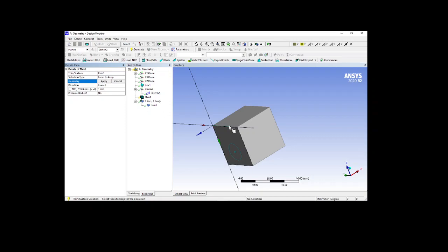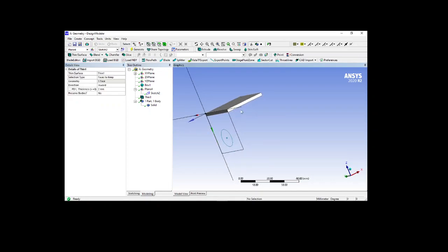Here it is telling us to select the geometry. Select the face. I will select it and apply. This is the inward of 1 mm. I want 2 mm. Next, if I generate this, it will create a thin face on that body, by eliminating the previous body.